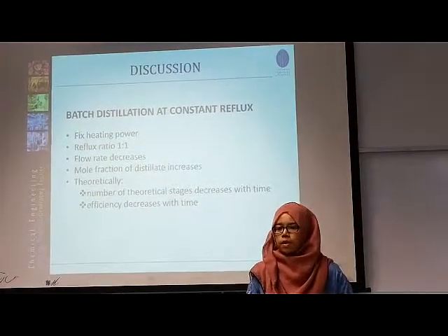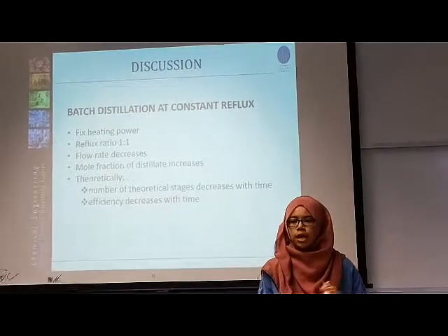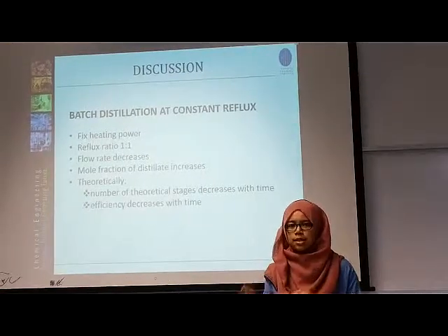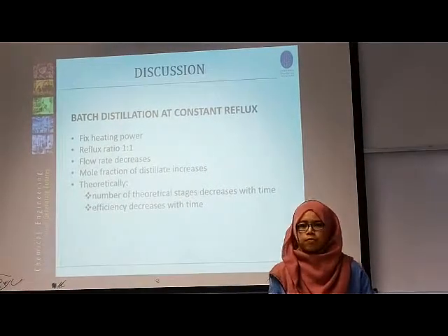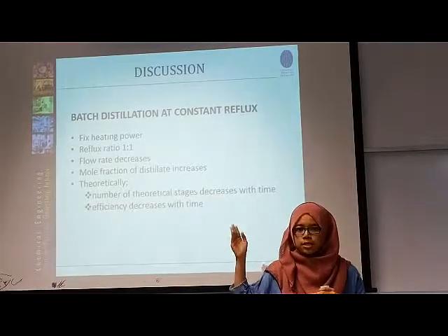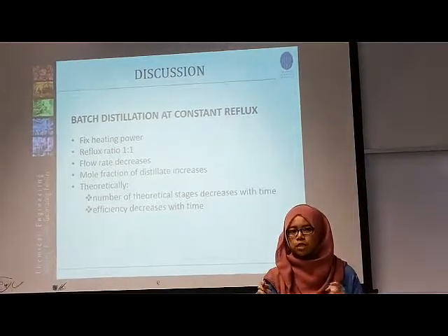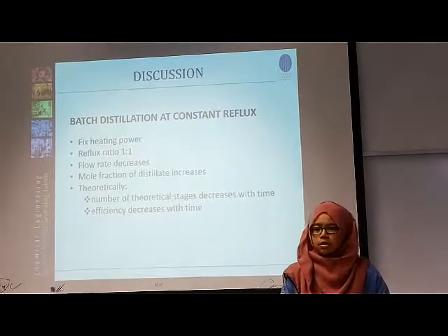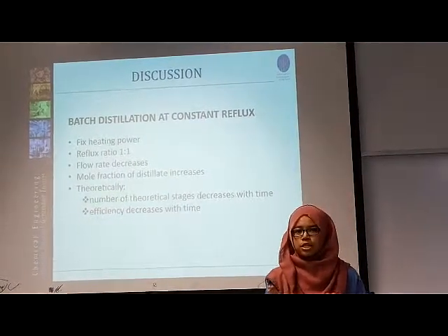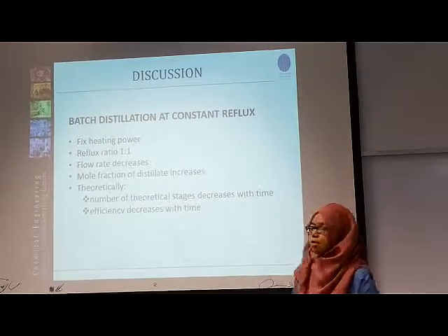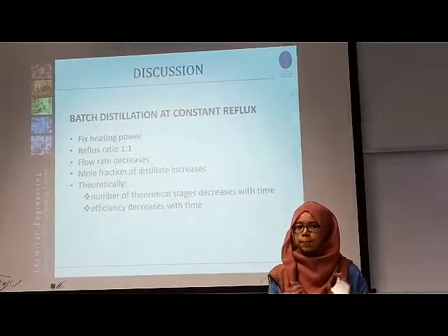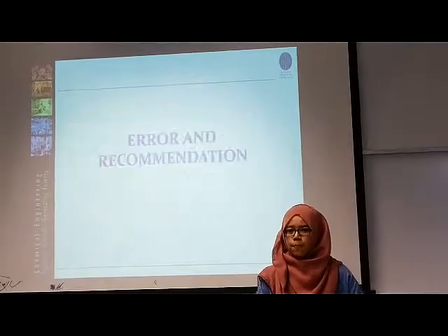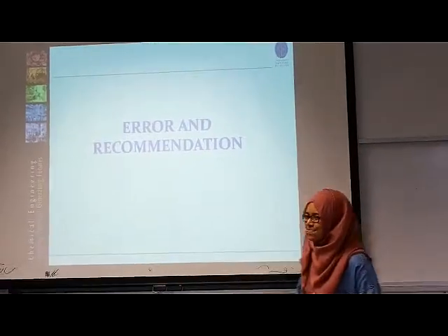So we calculated the flow rates manually, and from our observation the flow rates decrease as time goes by. The mole fraction of the distillate also increases, whereas the mole fraction of the bottom product decreases with time. Theoretically, the HETP value will increase, which means that the efficiency will decrease with time. So I'll pass the floor to Ambi. Thank you.